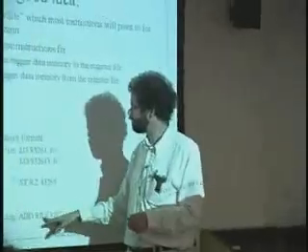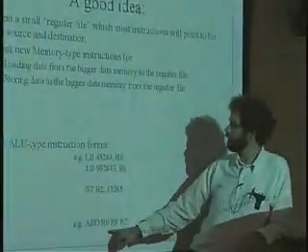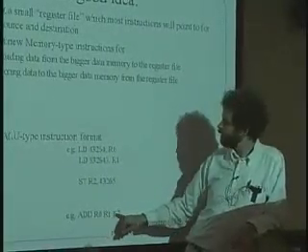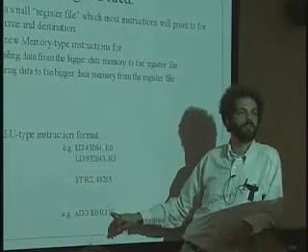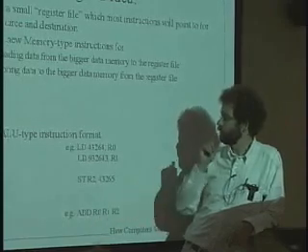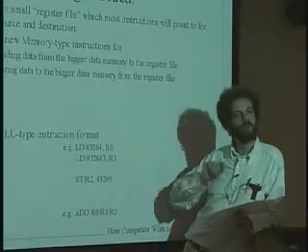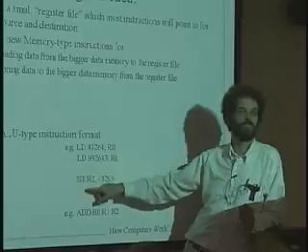So what kind of instructions do we have now that we have this small, fast system and a big, slow one? Well, instead of adding a pointer and another pointer, putting the result in the third pointer as we had before, now we're going to say things like add register 0 to register 1, putting the result in register 2. And this number at the end of the register will never get more than 31. It has a range from 0 to 31. We're also going to need some specialized instructions to do motion between the big slow system and the small fast one. And that's going to be called load and store.